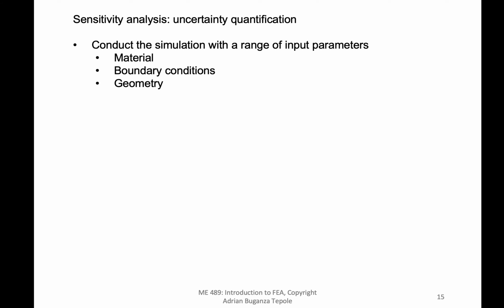And then another thing that you want to do is sensitivity analysis, or uncertainty quantification. You want to make sure that you do simulations with a range of input parameters. So not just a single set of parameters, but you want to change the material properties, the boundary conditions, the geometry, and you want to see how sensitive your solution is to these changes.